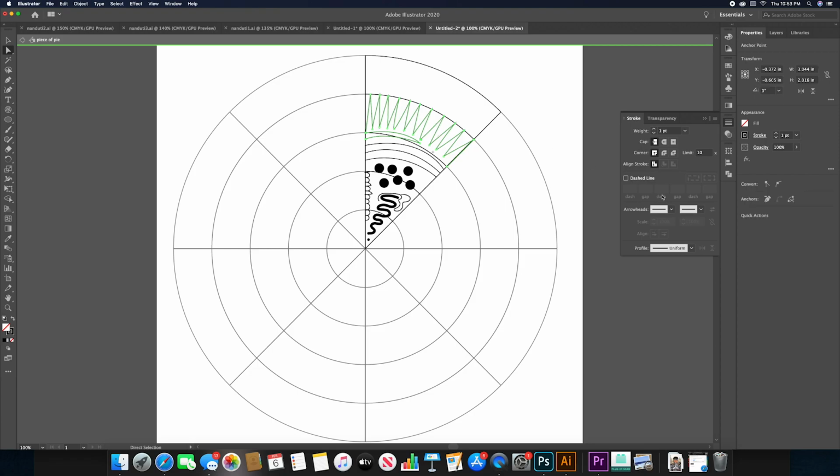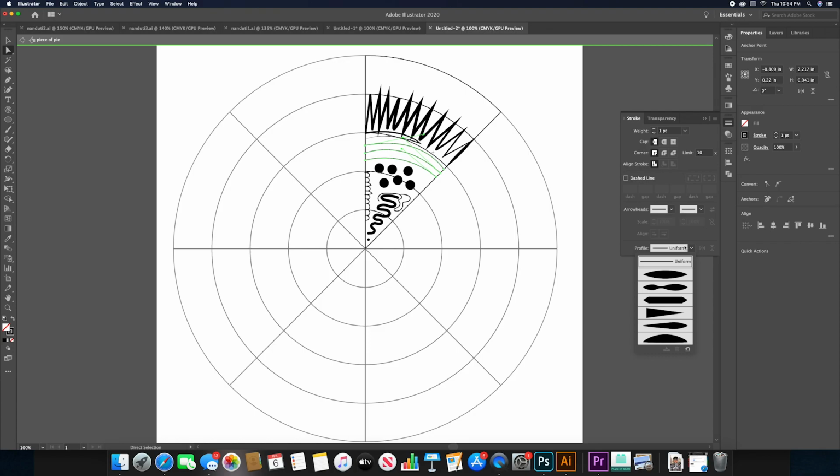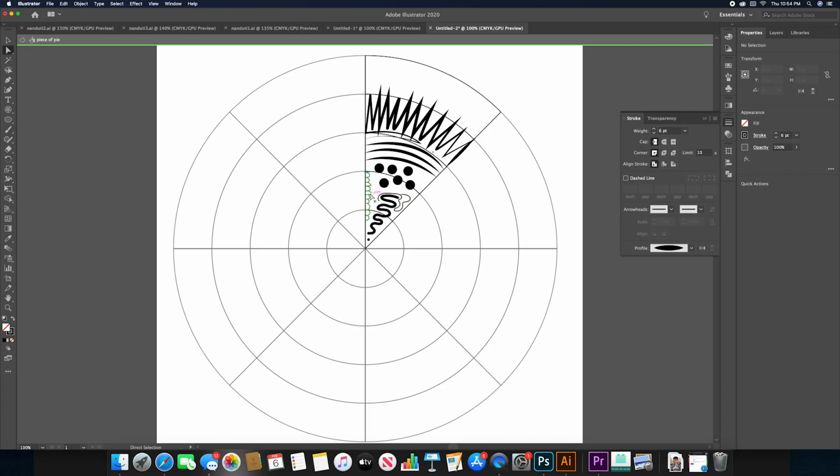I can also look to change the thickness of the stroke. If I go over to the stroke panel on the right side, I can change our uniform stroke into a thin to thick stroke. If I adjust my stroke, you can see how it goes from thick to thin in different various areas. I can select multiple lines holding down Shift, and again look to modify the thinness or thickness of the stroke, creating a little bit more interest, something more dynamic.